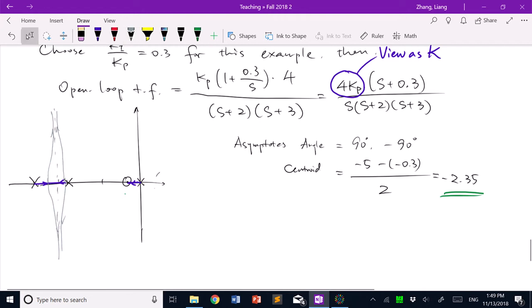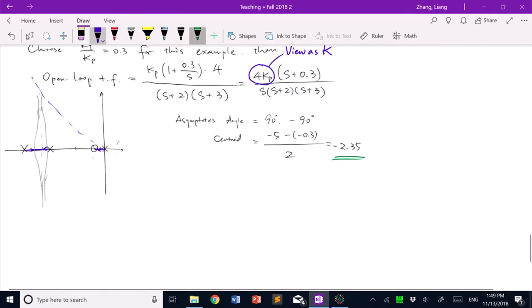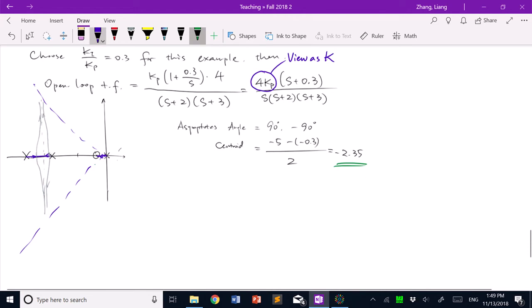We know that to do the control design, especially when you look at the overshoot, we just look at the angle. 5% will be tuned down to 4.3% such that you have this 45 degree. And you'll find the intersection either there or there, doesn't really matter. You still want this to be the 45 degrees such that you have the overshoot being about 5%.